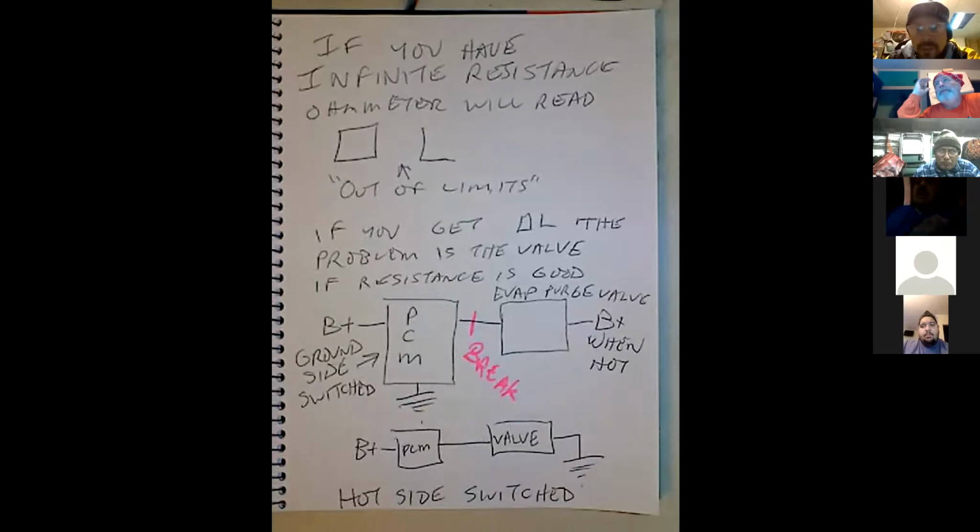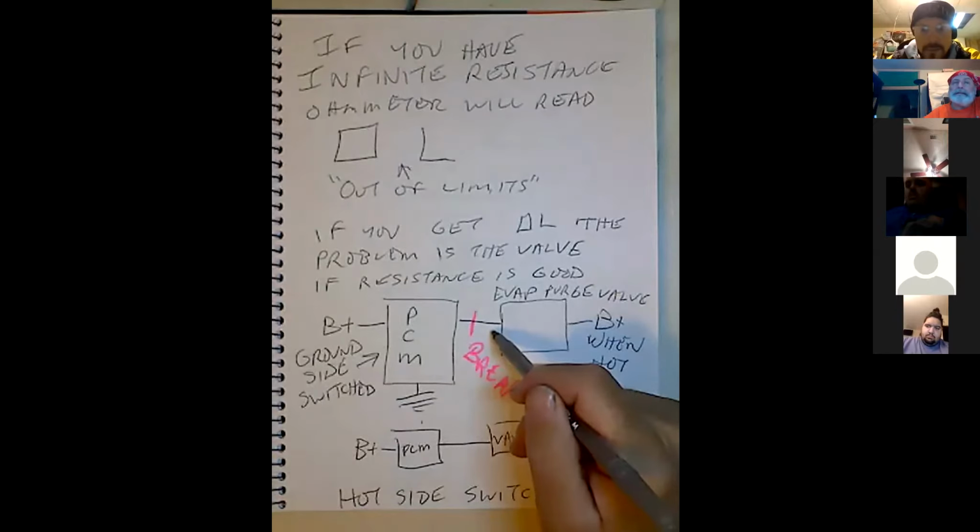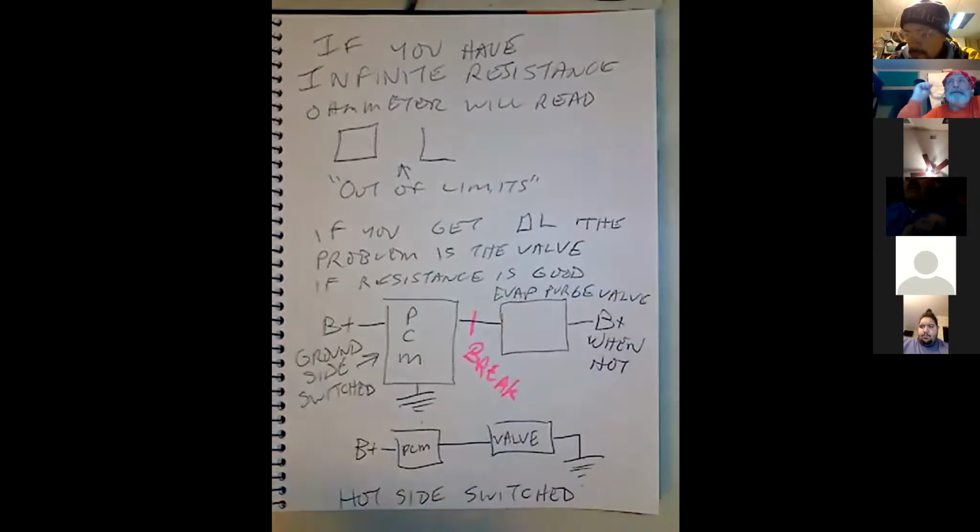I'm remembering now. We did that with a power probe. We checked the valve. The valve works. And not only did we check the valve electrically, but we also checked it. Is that true, Tony? Yes. Right. So I would suspect a bad connection. I think it's going to be a bad ground somewhere.